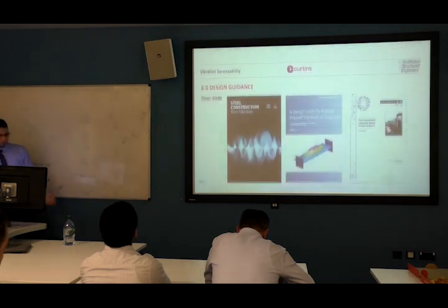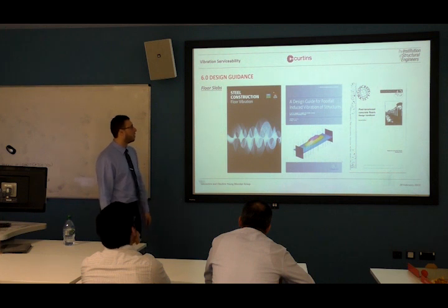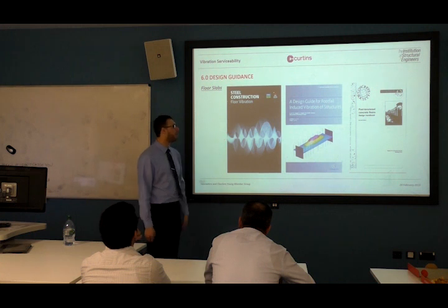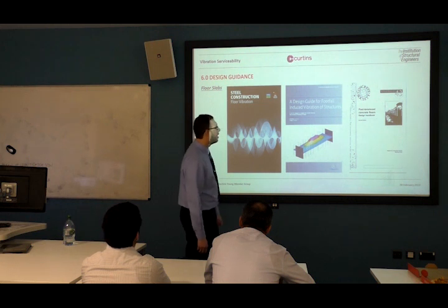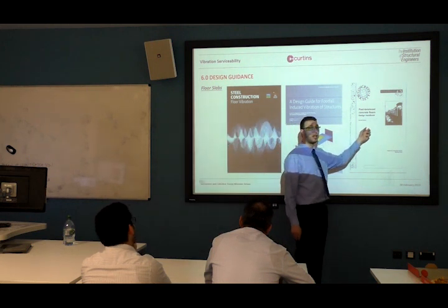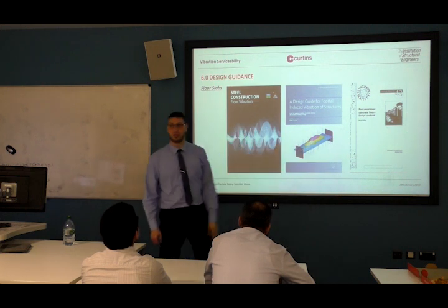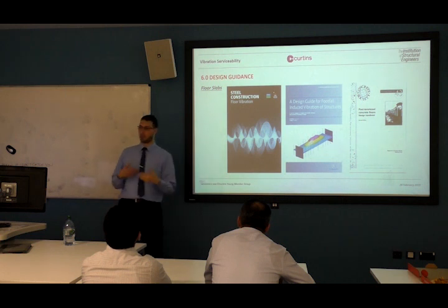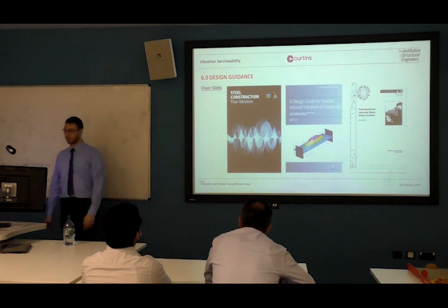All right. So last thing to talk about. If you are looking for guidance for floor slabs, we have a multitude of them. We have P357 from the Steel Construction Institute. We have this grey book from the Concrete Center, and this is actually CSTR 43. It's very, very good. I can't stress how good this one is. Appendix G: everything you need, from theory to application, is in that Appendix G.